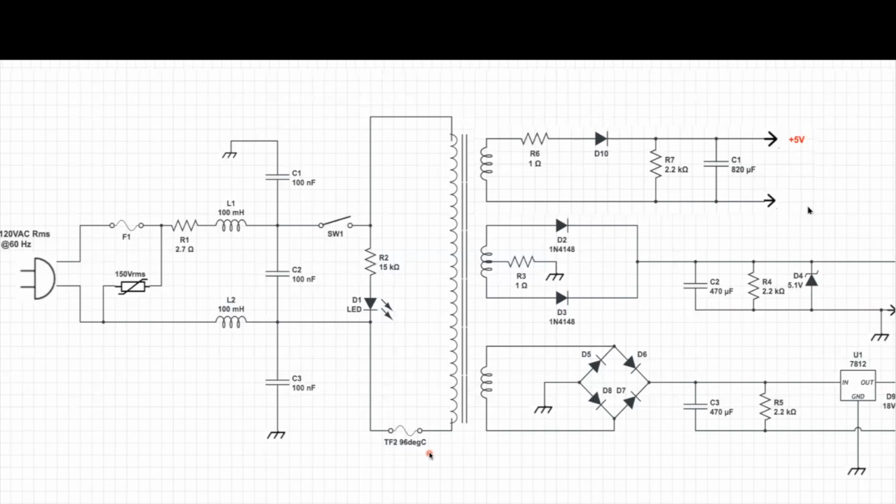Now, I said might. I want you to realize that everything that you see on the primary of this power supply might be there. I can assure you every power supply has a fuse. It has to. UL, Underwriters Laboratories, those engineers that set standards that electronic equipment has to be built by, basically say we need fusible devices on AC powered equipment. So if something shorts out, it doesn't burn the home down. That's important.